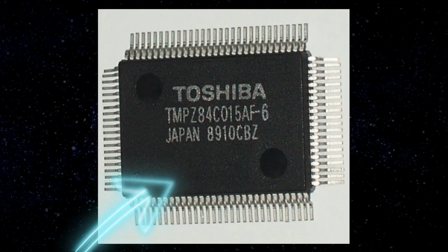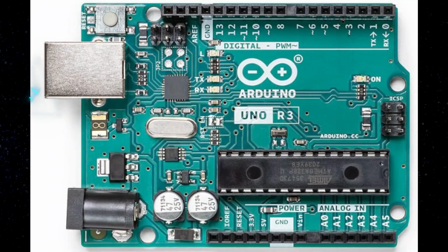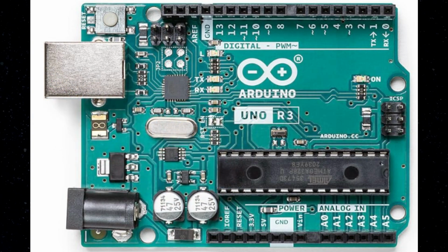All ICs are polarized, and each pin is unique in terms of its location and function. Most ICs use notches or dots so that you can tell which pin is first. The pin numbers then increase counterclockwise around the chip. This black box is the Arduino's IC package. Microcontrollers are a kind of integrated circuit, and when we call the Arduino a microcontroller, this is the specific part being referred to.